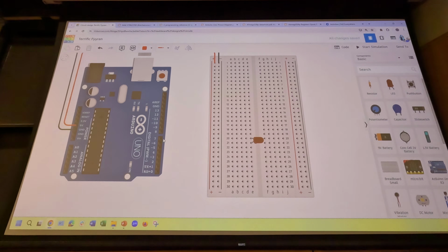Now, I am going to connect mine to Arduino pin 7. I want you to connect it to a different pin. Do not use pin 7. So you can follow the process I am doing when we look at the diagram, but you are not just literally copying what I'm doing on the screen without understanding what's going on. Okay, so I'm going to connect the jumper wire from pin 7 to the positive side of my LED.